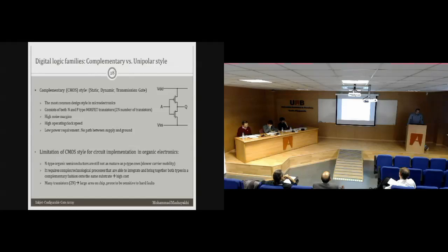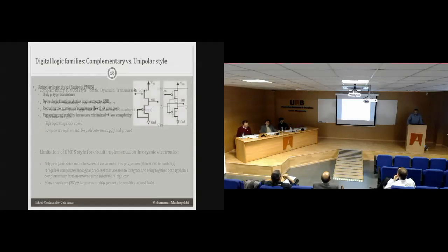Furthermore, there are many transistors for realizing any gate. It means that you need to have both the drive and load networks realizing the gates in parallel. So there are 2n transistors, where n is the number of inputs, so it occupies a large area on chip, and it is prone to being sensitive to hard faults.